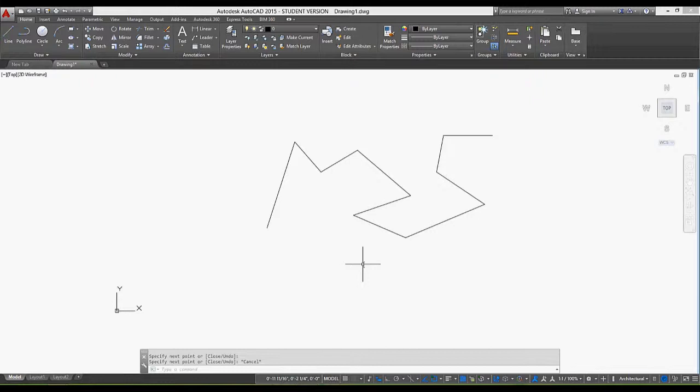So once you've gotten used to this, mastering the new commands will come much more quickly and easily. So in short, first select your command, then select the locations, and then hit escape to exit out of that command. And again, hitting escape aborts any command you might be in at any given time.